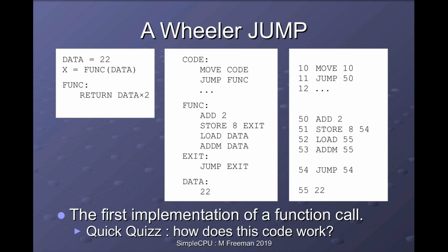In later versions of the simple CPU, we removed the need for self-modifying code, because obviously that's a bad idea, and introduced two new instructions, the call and return. But these do come with a hardware cost. We need extra architectural units to implement these instructions.